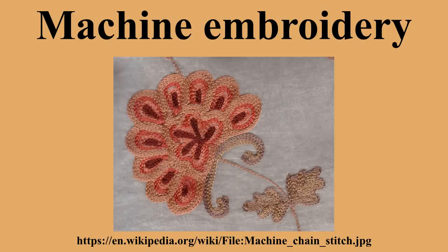Design files. Digitized embroidery design files can be either purchased or created with industry-specific embroidery digitizing software. Embroidery file formats broadly fall into 2 categories. The first, source formats, were specific to the software used to create the design. For these formats, the digitizer keeps the original file for the purposes of editing. The second, machine formats, were specific to a particular brand of embroidery machine. Here, the files are available for use with particular embroidery machines and are not easily edited or scaled.